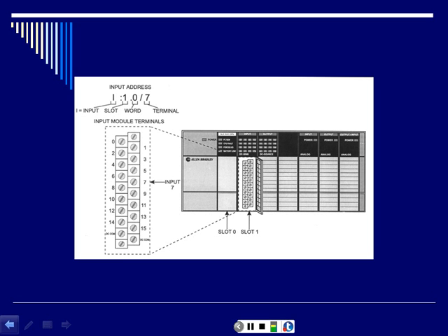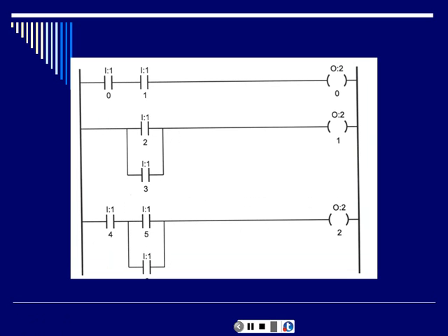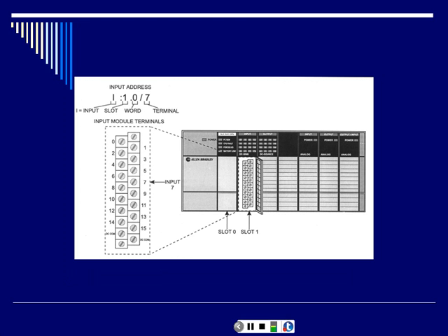This is basically the way that the screws look, okay? When I'm addressing these, and you notice back on my addresses, I set that thing down all the time. On my addresses, see the I:10? What that means is this is an input. It is an input in slot 1. This right here is your power supply. It's not considered a slot.